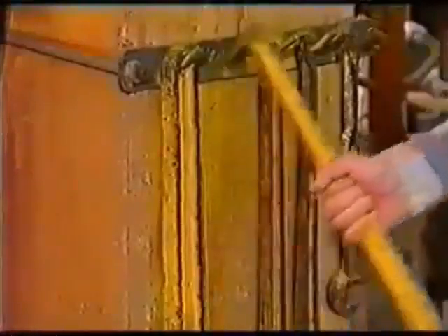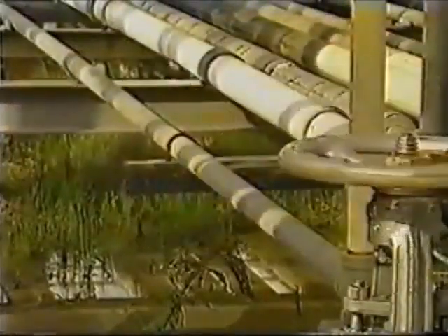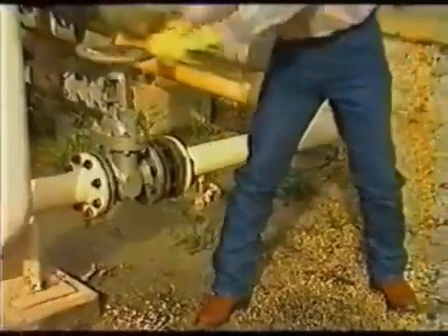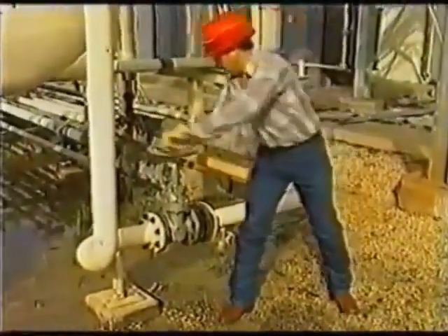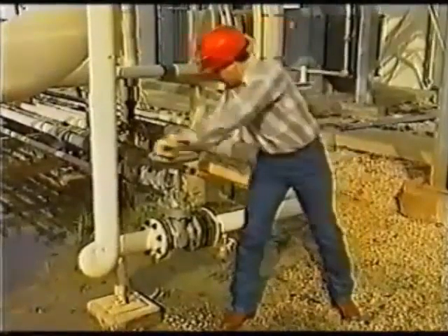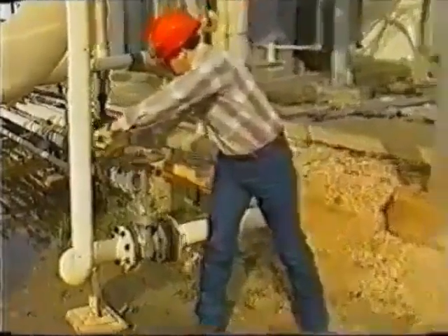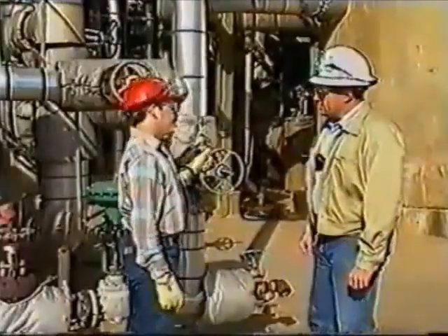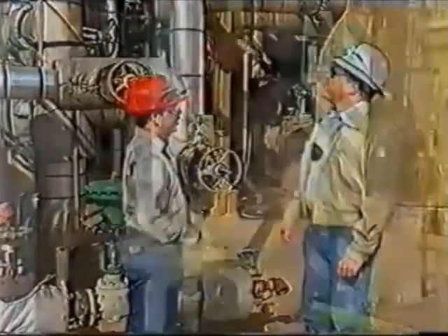Choose the correct size wrench and securely attach it to the hand wheel or spokes so that the wrench will not come off when force is applied. When applying force to the wrench, make sure your weight is evenly distributed so you don't fall when the valve opens. Wrenches should always be pulled towards you to prevent ramming your fingers when the valve gives. If you encounter difficulties or have any questions, notify your supervisor.